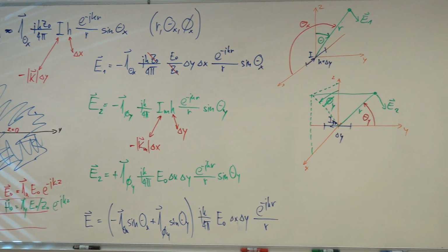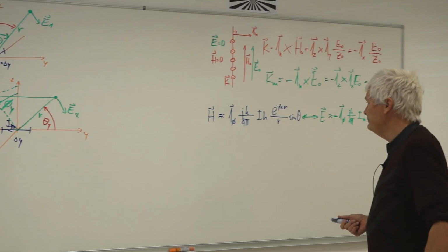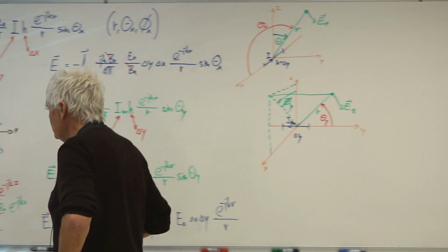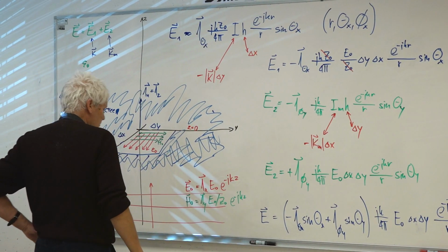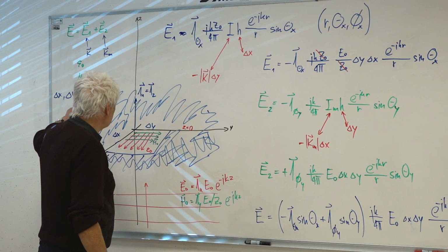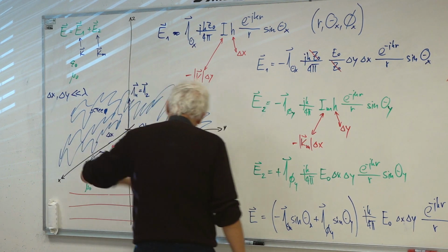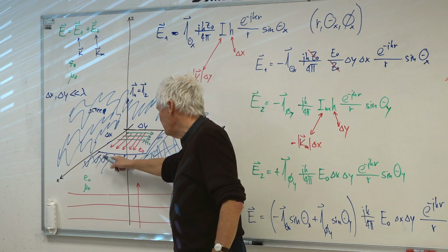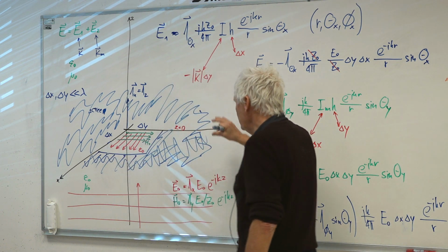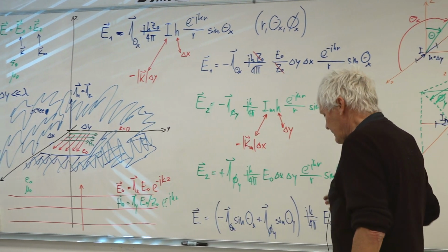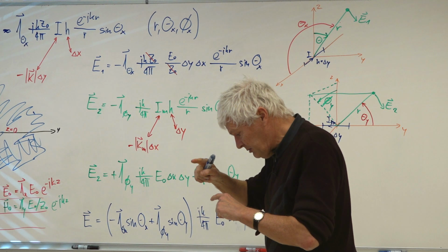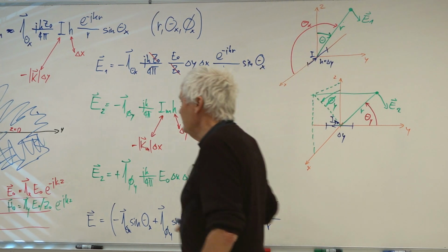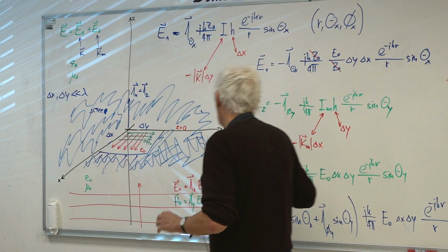So we got the result for the electromagnetic current source, where delta x and delta y are much smaller than the wavelength. We should be careful about this because if we really make such a source, such a small aperture in a screen, there will also be edge effects on these currents flowing on the screen. So this is only useful in the same way as the current segment we had, which had charges on both ends. Here we have currents in the screen. So this is only valid when we integrate this over the whole surface. And that's what we intend to do.